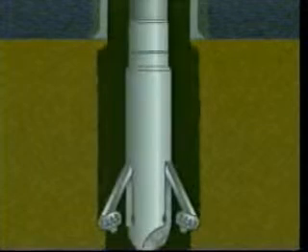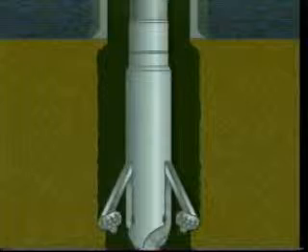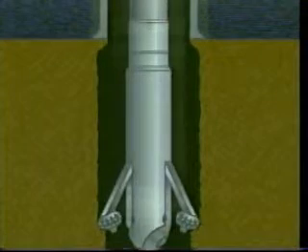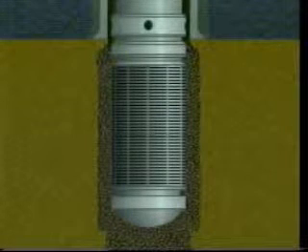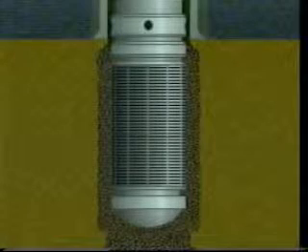Now, let's turn our attention to gravel packing, the most common and generally most effective method of sand control. As mentioned before, there are two basic types of gravel packing, the open-hole gravel pack and the cased-hole gravel pack. In the external or open-hole gravel pack, the casing is set above the pay zone, and the open-hole wellbore is then under-reamed to maximize flow area. The gravel pack screen is hung as an uncemented liner, and the area between the screen and the formation is packed with the appropriately sized gravel.